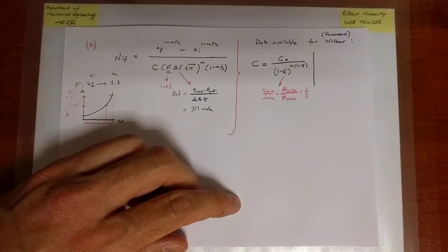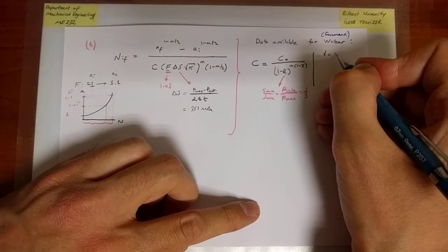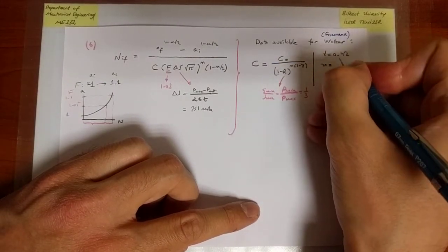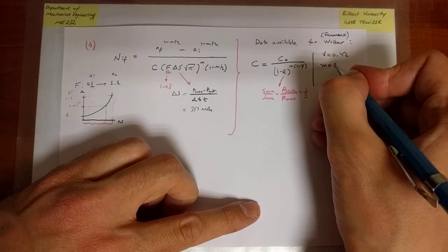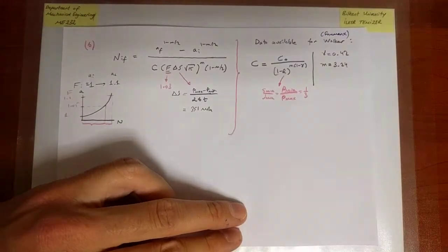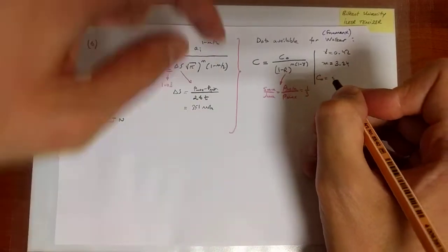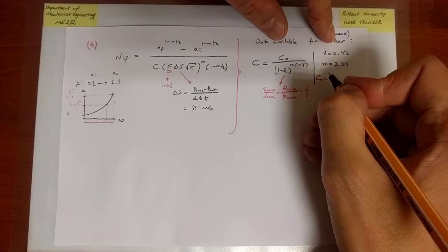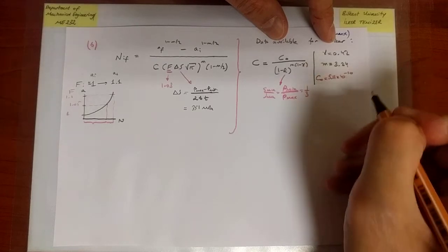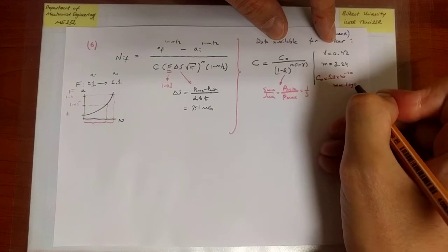That's not a material parameter. The rest are. So gamma, it depends on the material, but also the type of loading, is 0.42. M is, so these you have to read eventually from the table where you make your choices. M is 3.24. As I said, it's usually not equal to 2. Now I'm going to write C naught in red so that you are careful about C naught. The value of C naught is equal to 5.11 times 10 to the minus 10. And I'll write the units here. It is millimeters per cycle.